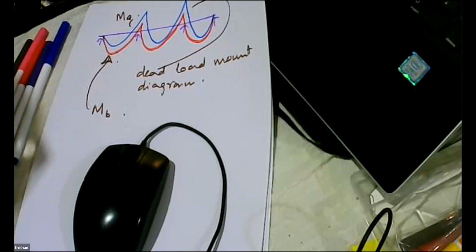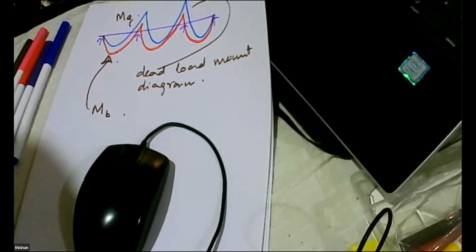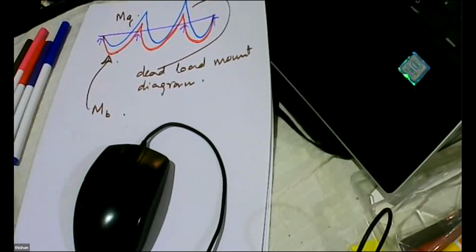In continuous bridges, creep can change the curvature. Shrinkage can change the curvature. Thermal stresses also can change the curvature. So when you are calculating those effects, this matrix-based method becomes very useful, right? Because of that reason, next week we will spend a little time deriving this equation.